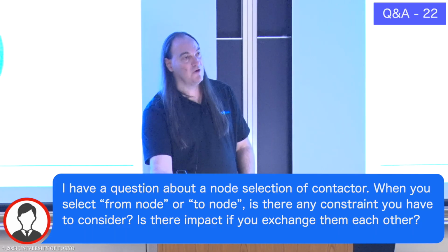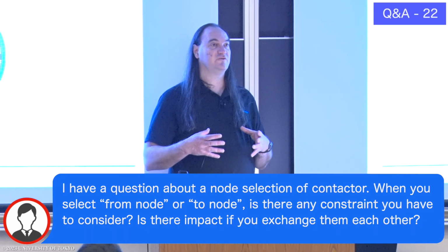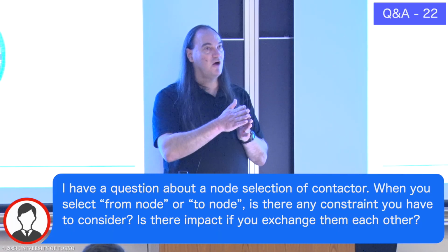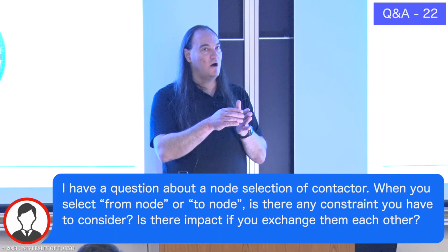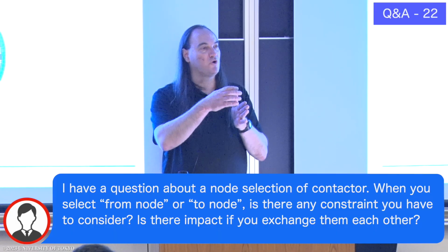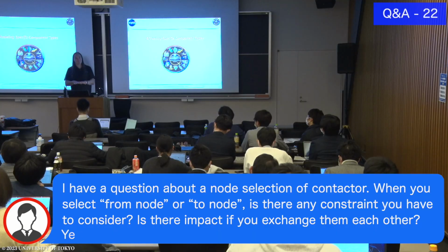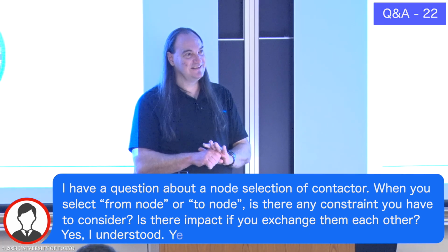It would only be 1 or 2 that make contact here. So generally speaking, it's best to go from the smaller surface that you're subdividing to a small and fine enough granularity that you catch large portions of the sub-mesh underneath it. Make sense? Did it answer the question? Okay.